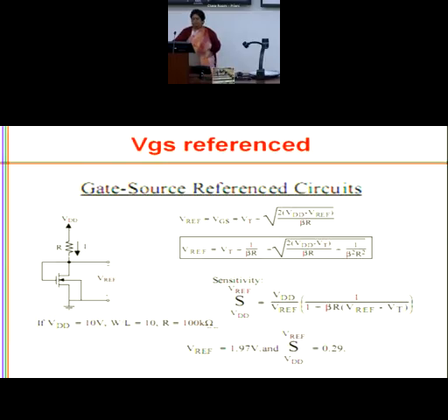Okay? So now we have got a Vref. Deliberately we have written I in terms of VDD. Why? Because we want to look for the sensitivity of Vref with respect to VDD. This is what I am interested in. And mu and C of W by L we are assuming they are all constants, so I am clubbing them together in the form of beta.